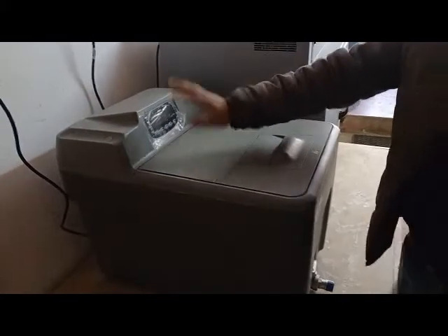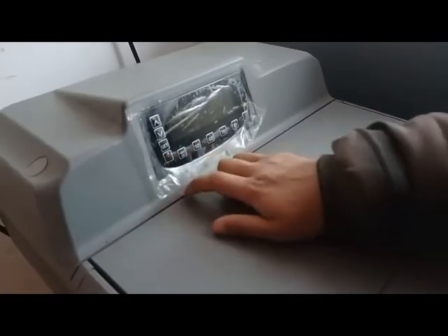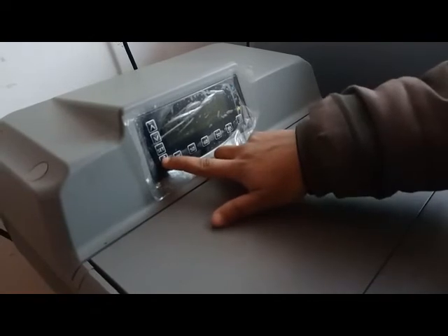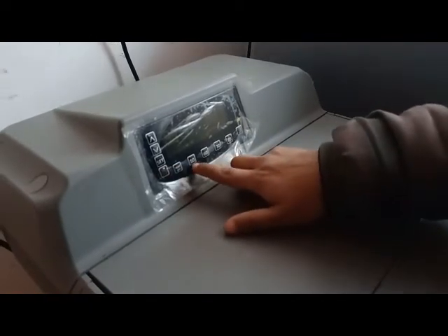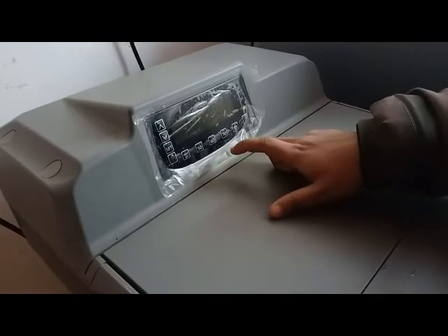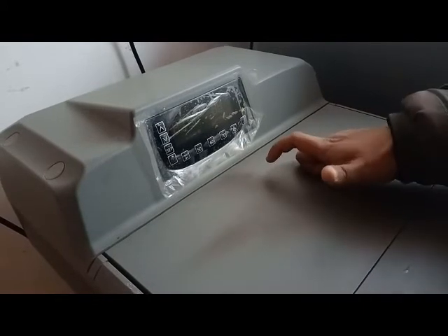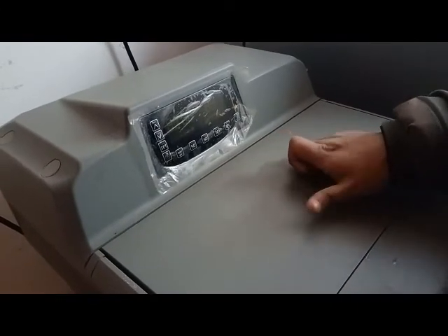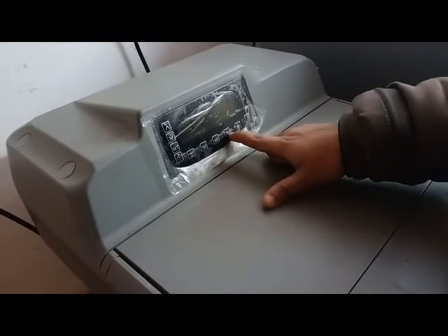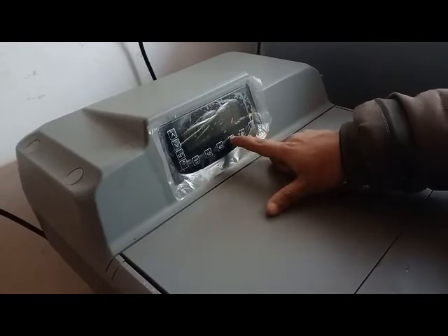So you can see, I'll just simply show you. So this is the power button. We simply will switch on the power button, and it will show whether the heater is off or on. So if we switch it on, the heater will be on, and here 50, 60, 70 and 85 are the temperatures, which temperature I need, because we have 4 different materials, that is ABS, ASA, TPU and PLA. So for those we have different temperature ranges. So we will simply keep it around 70 to 85 in between for ABS and ASA, simply this one.